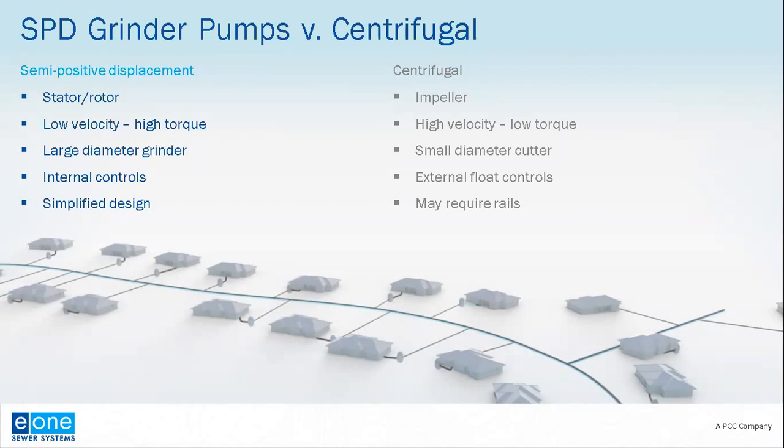We really put a lot of emphasis on this aspect of the design. You can see a lot of videos on YouTube showing pumps chopping up a pair of jeans in 3 seconds. If you saw an E1 grinder pump demo, you would notice that it would steadily and slowly take little nibbles out of solids, grind it up and pass it along. That equates to more reliability. That's a design that's not going to get jammed up as easily because, again, it's more like a grist mill. It's operating at a low speed with a lot of power, a lot of torque behind it.